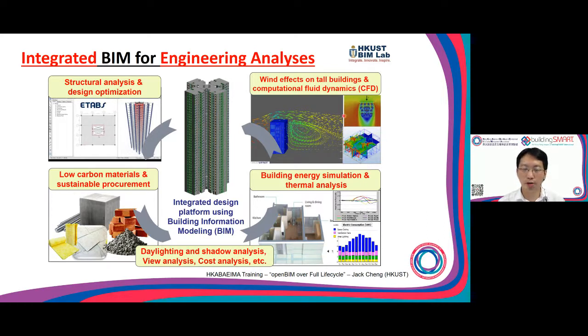Basically, we use Revit to draw the model, and then we export to IFC and link it to different software, like ETABS for structural analysis. We also link it with some CFD software to perform the analysis of the fluid, and then see the ventilation indoor and outdoor. We also look at the thermal analysis, so we plug this into some green building analysis software.